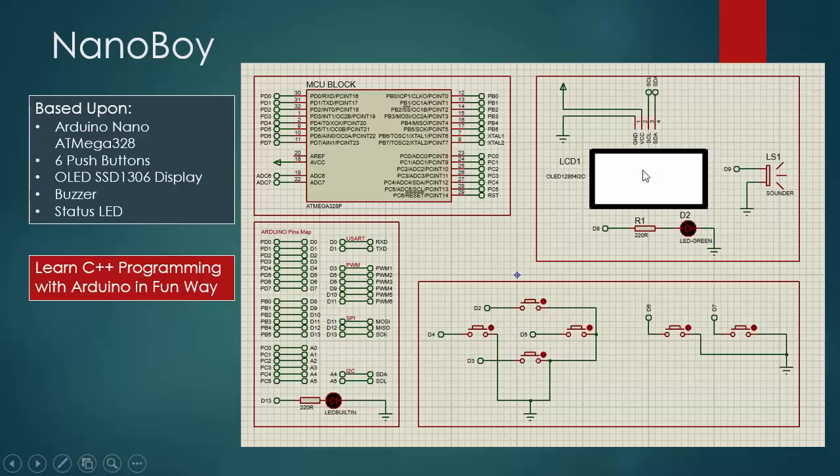Basically, it has this OLED display, which is connected to the SDA and SCL lines of the microcontroller, which are I2C lines. One LED, which is connected to the D8 pin, and one speaker, which is connected to the D9 pin. Then there are 6 buttons. 4 are arranged in the D-pad fashion: up, down, left, and right. And these are connected to D2, D3, D4, and D5. And then there are buttons A and B, which are connected to D6 and D7. That's it. That is the only hardware which is present.